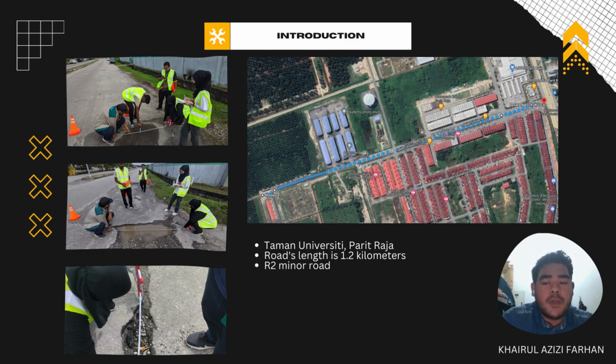A good road pavement is made up of numerous layers of processed and compacted materials in both bound and unbound forms. Damage to road pavement is typically caused by traffic loads, temperature, moisture content, or subgrade movement. These categories of damage include pavement cracks, surface deformation, surface defects, edge defects, potholes, and patches. In order to determine the levels of road damage, we use the pavement condition index.